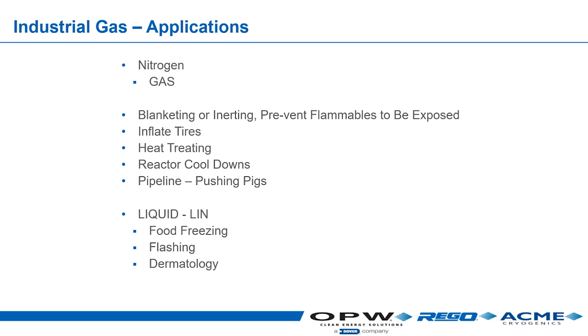That's the theory of flashing. Or a lot of times they'll put all the parts in a strainer, lower the strainer into liquid nitrogen, then take it out, and then break off with a hammer all the parts on that piece that don't make it compliant.